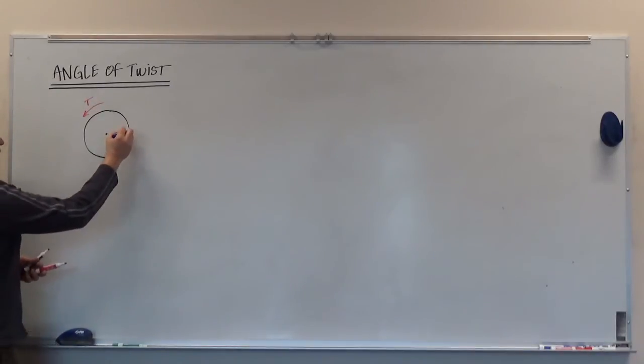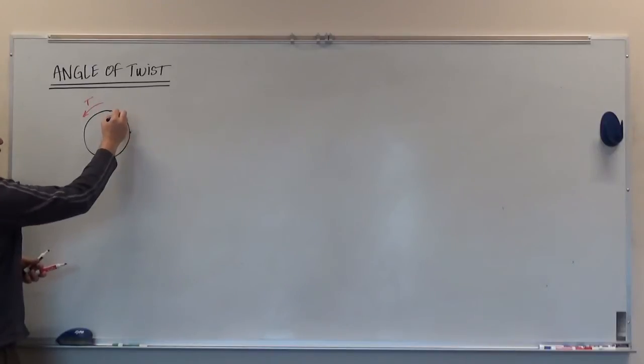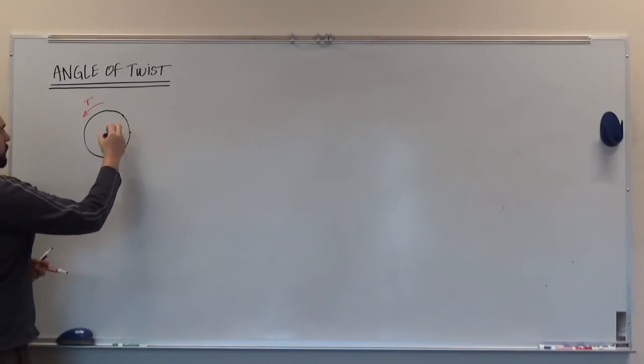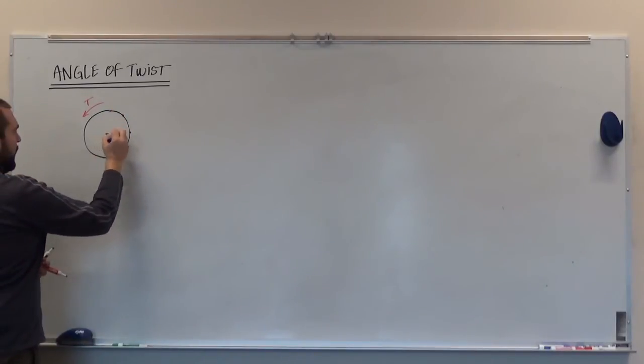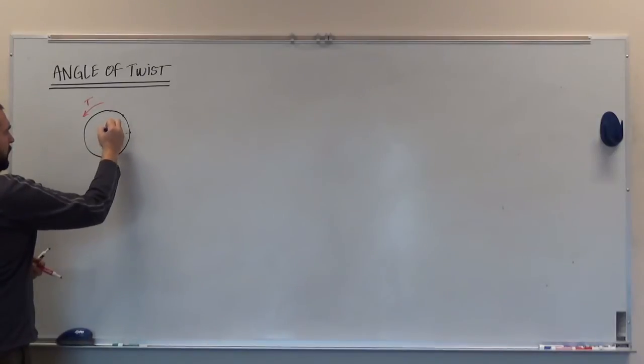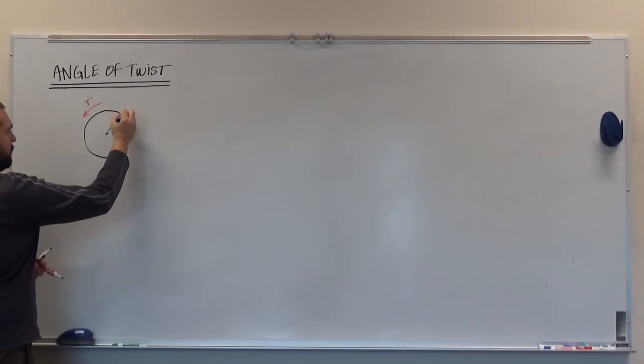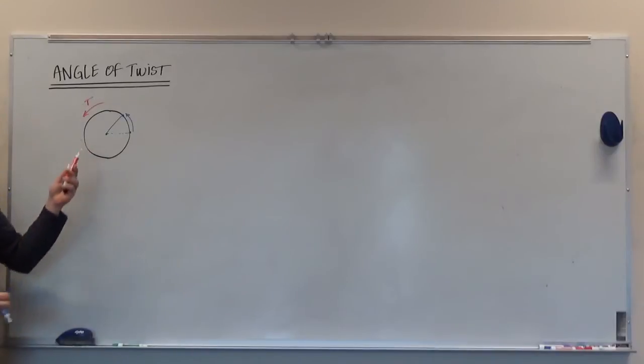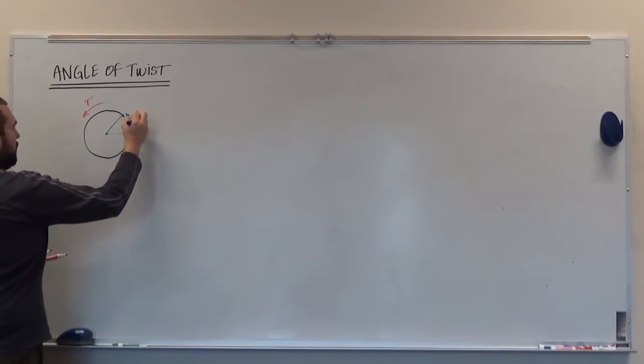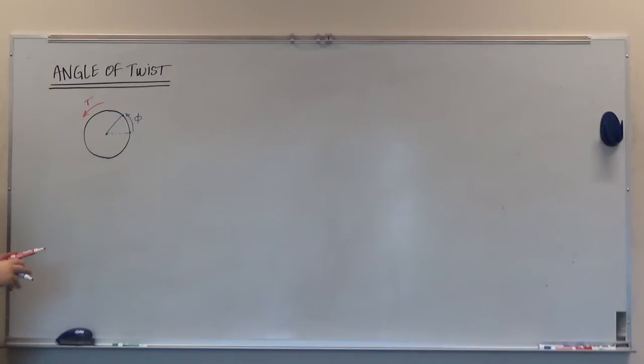We're going to find that this point that I painted on is going to move some amount right here. And so it started out relatively horizontal, it rotated up, and so on this cross-section we have some angle of twist phi. But to get to the angle of twist phi, it considers what happened on all the other cross-sections, in or out of the page.